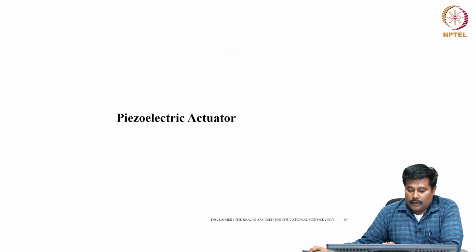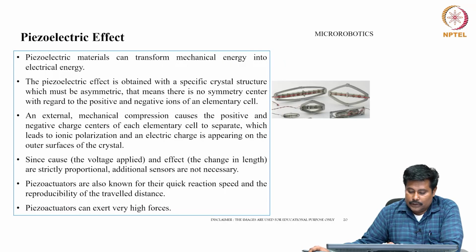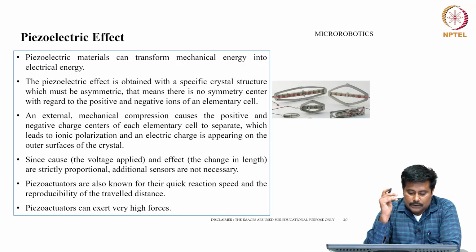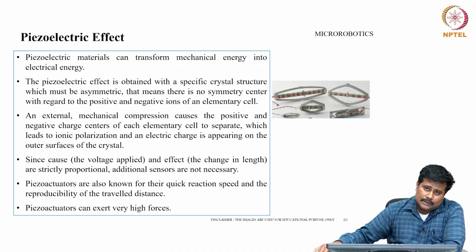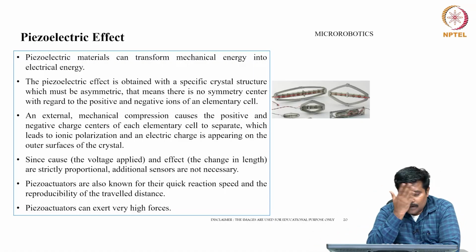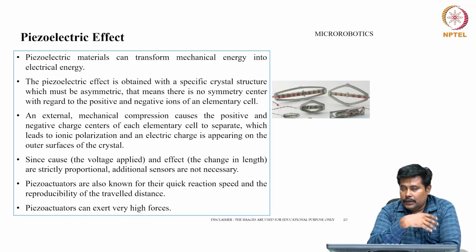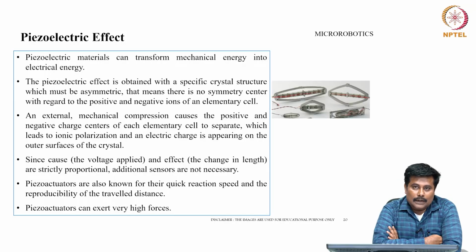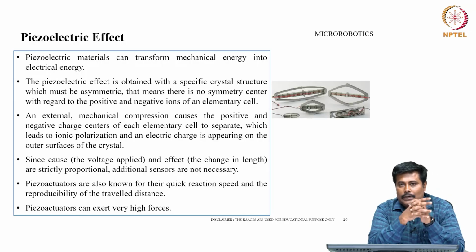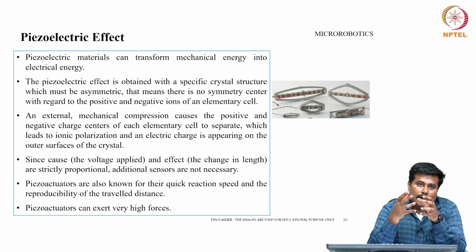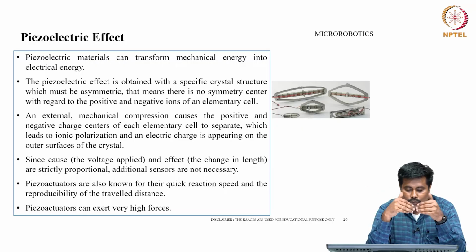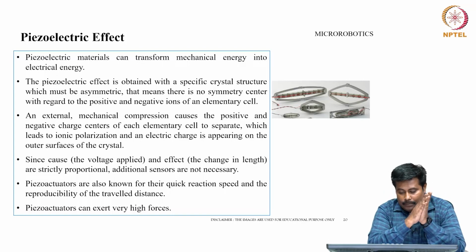Now, from the piezo actuator perspective, magnetostrictive and piezoelectric almost work on the same functionality. However, piezoelectric has a wider application. In fact, more than 3 to 4 decades people have been working on these piezoelectric structures, since this piezoelectric material can transform mechanical energy into electrical energy, and this piezoelectric effect is obtained with a specific crystal structure which must be asymmetric. That means there is no symmetry center with regards to the positive and the negative ion of an elementary cell.